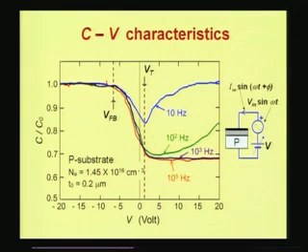Let us look at this curve. Now like it is difficult to locate the threshold voltage on the high frequency CV curve, it is difficult to locate the flat band voltage on the CV curve. Both low and high frequency CV curves at flat band point and below flat band point are same. This is because you really do not know where the curve has started increasing. Though we have shown the flat band point to be somewhere here, you really cannot locate it precisely. You can even move it to the right, okay? So we do not know exactly where the flat band point is.